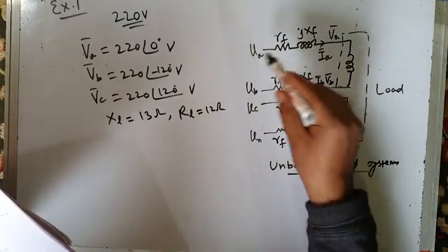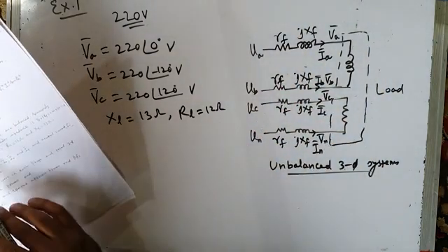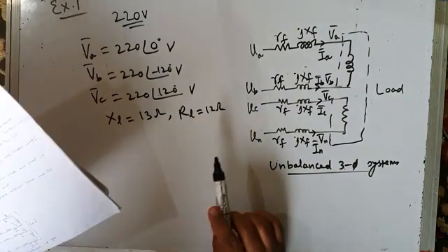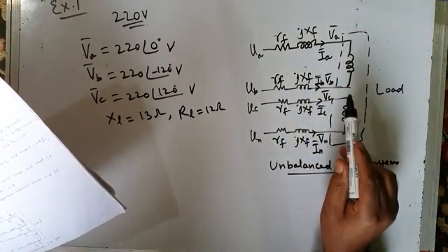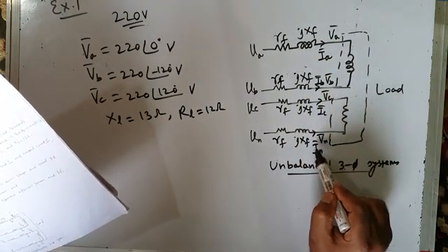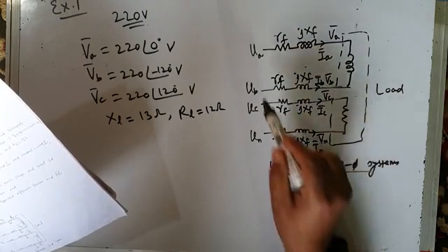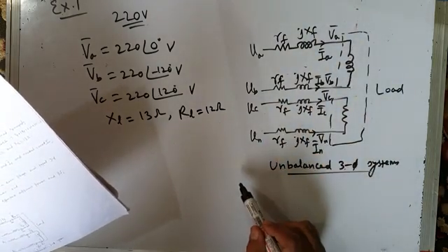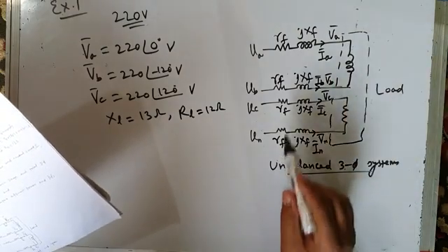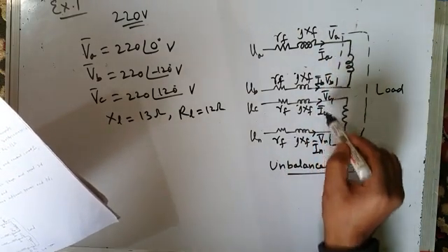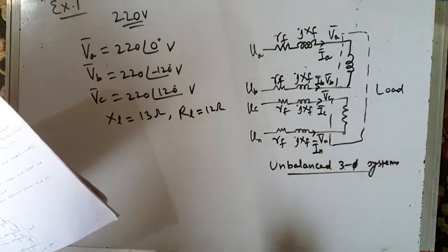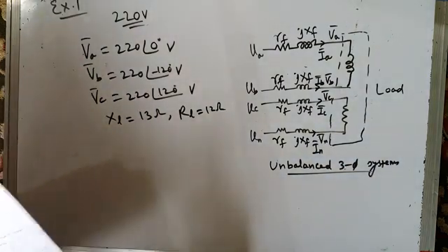See, this is a sinusoidal three-phase system. It is written for us three-phase sinusoid. VA, VB, and VC are balanced sinusoids. So there are no harmonics. Okay, had the system been balanced, the neutral current would also have been zero because the voltages and currents are sinusoids. But because of unbalance in the load, the unbalanced currents IA, IB, IC will flow, and this unbalance will result in the flow of neutral current. So we have to find all that.